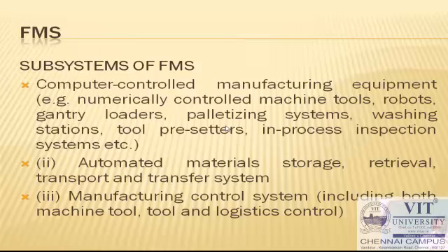For a first component, 10 machines are required. For a second component, if only 6 machines are required, then while making the second component you can flexibly rearrange your machine shop. Either you can change the machines, or you can change the routing, the conveyor system, or the material handling or work handling system. So that is called a flexible manufacturing system. Flexibly you can change or modify the manufacturing resources that are available. This can be obtained by using computer controlled equipment.